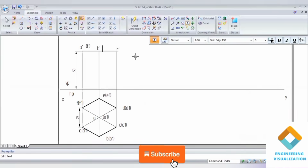So from the front view, A dash, B dash and C dash are visible, D dash, E dash and F dash are not visible. Not visible means we should write within brackets. In the same way, for the bottom face also we write the same thing.